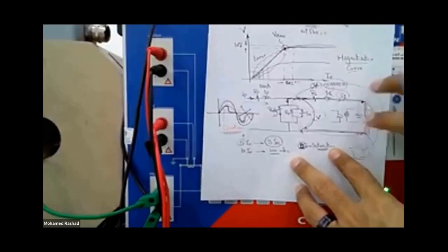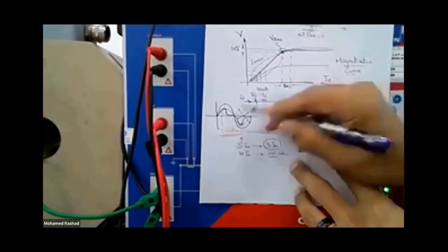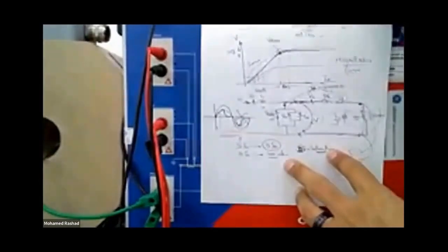What will I inject here? Voltage. And I will raise the voltage and measure the current, raise the voltage and measure the current. So what is the current being drawn now in this circuit? This circuit now is completely disconnected and not connected to anything. So the current being drawn in the entire circuit is just the magnetizing current of the core. So I will inject voltage and measure the current, again and again. Of course, the current is measured in series from within the device itself.